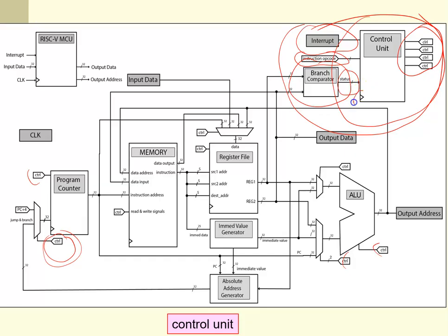It does have a clock signal here. I should say that. Here's your clock. I didn't really connect it to anything, but every time you see this triangle here, it indicates that this device is edge sensitive. So the things that happen in the circuit happen on a clock edge, and this is particularly a rising clock edge in here.